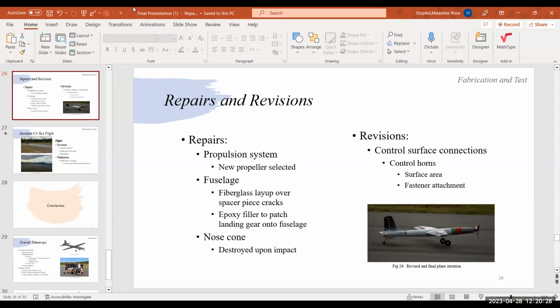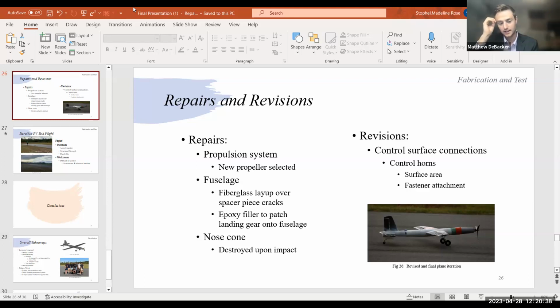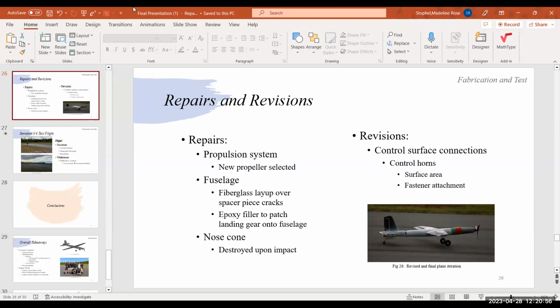Is there a way you could do that analytically in the design phase, before you even have a motor selected? Sure. You could use conservation of energy to get the heat coming out of the ESC. And then if we had airflow, use the conservation of energy equation to calculate how much heat transfer from the ESC to the air there would be. Okay, yeah, that's what I was looking for. I'm not going to press you too much on it because the flight time is only about 5 minutes and these are off the shelf parts. I just wanted to see if you had that in mind.